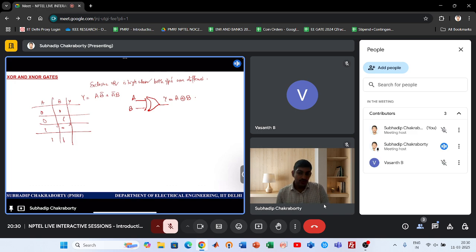so when both the inputs are different, you can see different inputs where this and this, then only it will be 1. Other places it will be 0. That is the physical significance. Only when both the inputs are different, then only the output will be on or high or true. So you can check also that if A is 0 and B is 1, then only the output is 1. Right? Because A bar is 0 bar, which is 1, into 1, which is 1.